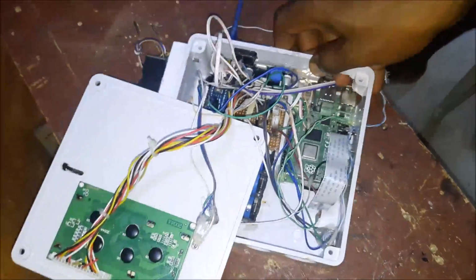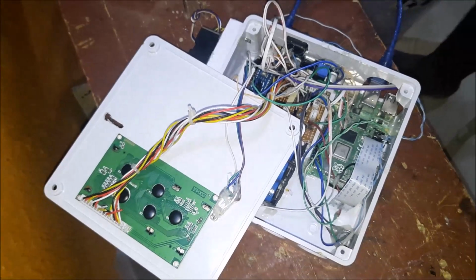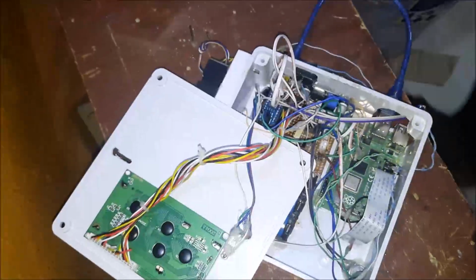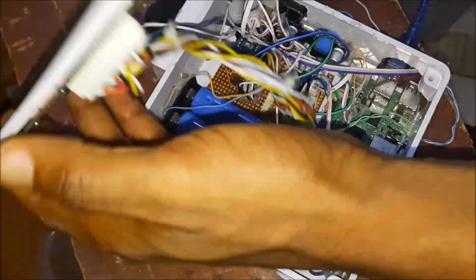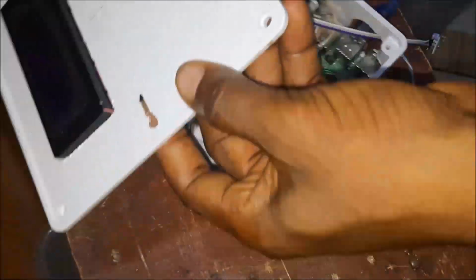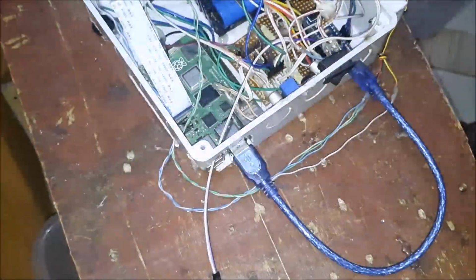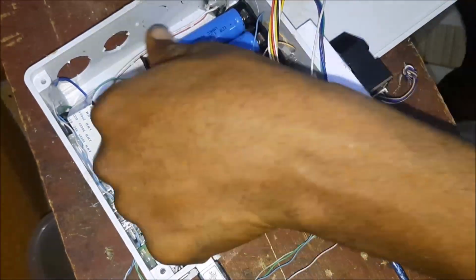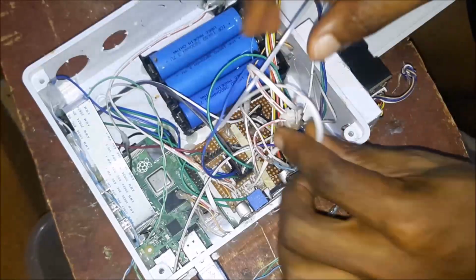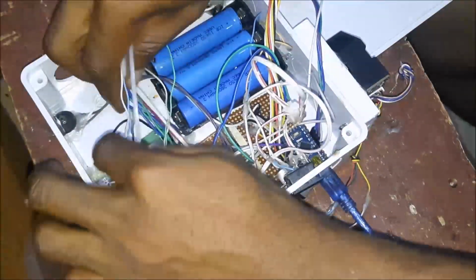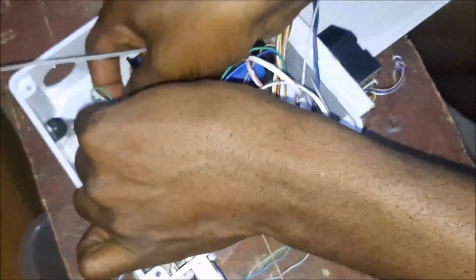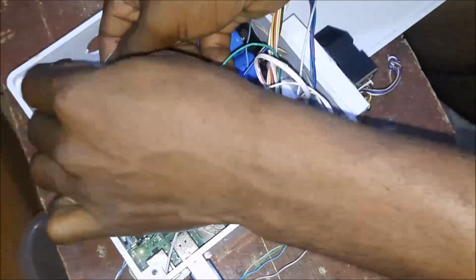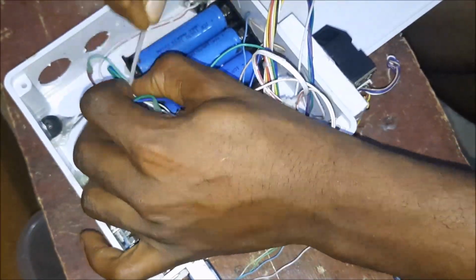For us, the Raspberry Pi 4B will take care of the face recognition and fingerprint biometric verification, whereas the Arduino Nano board will communicate with the Raspberry Pi through serial communication to display to the user what the project is doing and what it requires from the user. The project was designed to use a 20x4 LCD module. This will be interfaced to the project design and mounted on the top of the casing where it can show the user what to do.